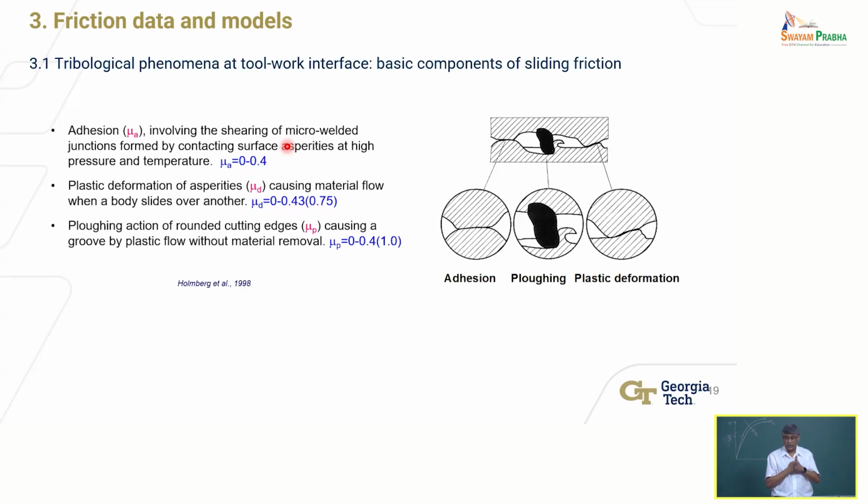So what is responsible for friction? There are these mechanisms, okay? Contact between the asperities. Asperities refer to these roughness peaks and valleys on a surface at some degree of magnification. And when you take two surfaces, this duster is sitting there on the surface. If I ask you what is the contact area between the duster and the surface, what would you say is the contact area?